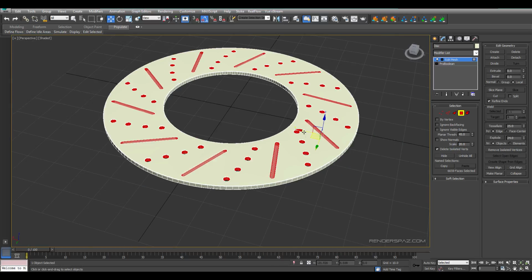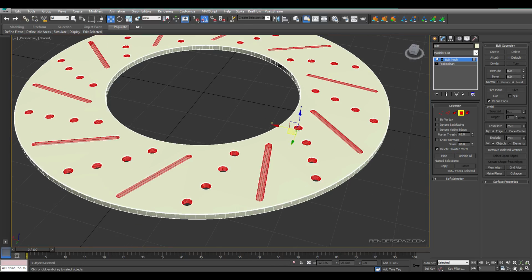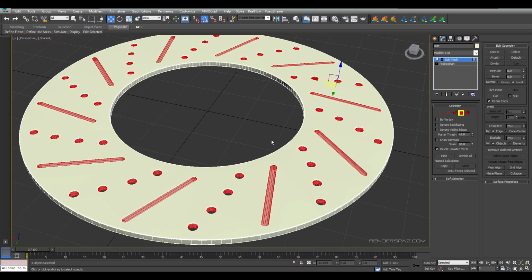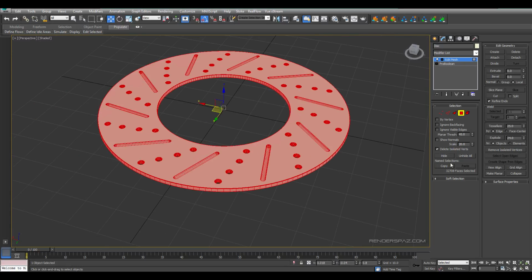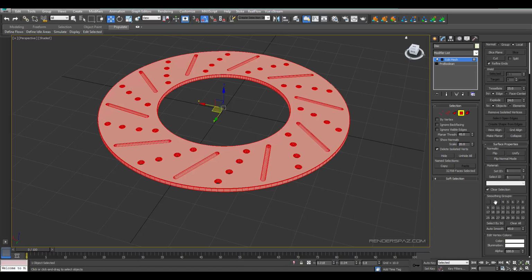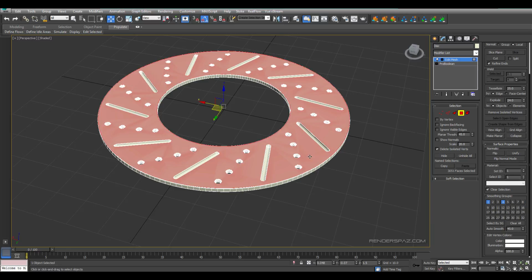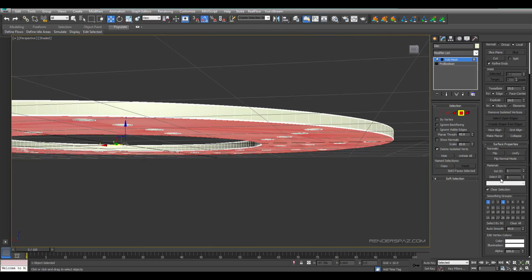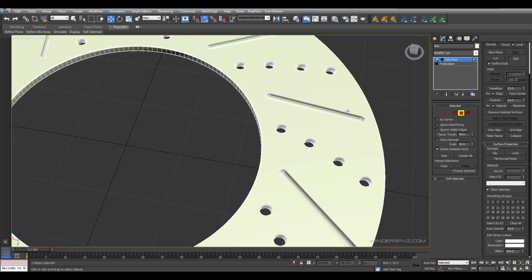Okay, so what we're going to do is we're going to select the whole entire mesh. Okay, we're going to put a smooth modifier, or not a smooth modifier, but we're going to throw in a smoothing group. Okay, but we'll select these guys here. Okay, and then we can just give them a non-smoothing group. This way nothing gets really funky there.